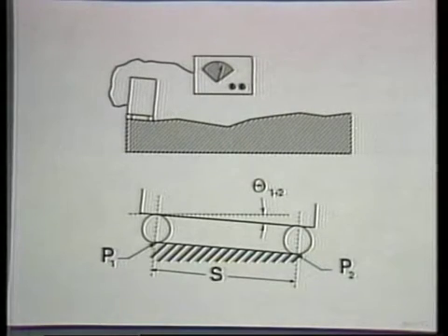To map a line profile, an angular measurement device is used to obtain the tilt of the measurement path segments defined by the spacing of the device's feet. In practice, a straight edge is normally used to ensure that the measurement path is followed. The measurement device is carefully positioned at the initial position. Two techniques can be used when initiating a series of measurements. The tilt reading at the first measurement position, that is, the tilt between points P1 and P2, can be zeroed, or the initial measured tilt can be recorded. A non-zero initial tilt value will not affect the final measured profile.